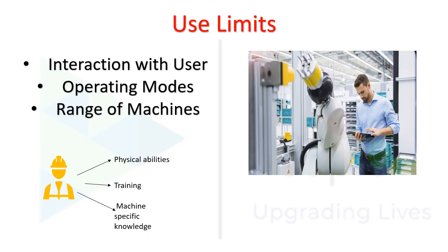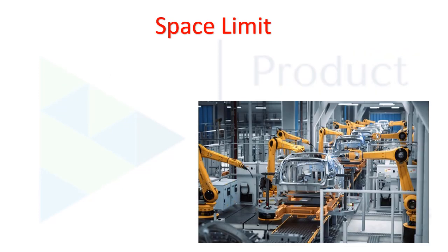A person may be very good at milling machine, but his knowledge may be limited in the turning machine. That again is a concern. A person without the specific knowledge, if he or she operates a particular machine, the risk can be much higher. All these things are basically covered in section 5.3.2 in ISO 12100.